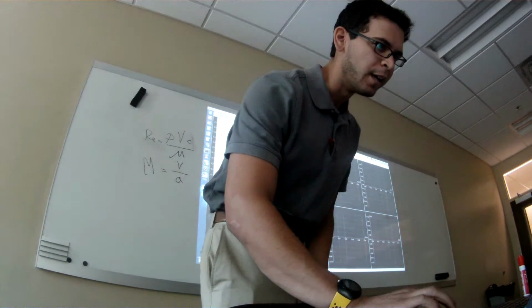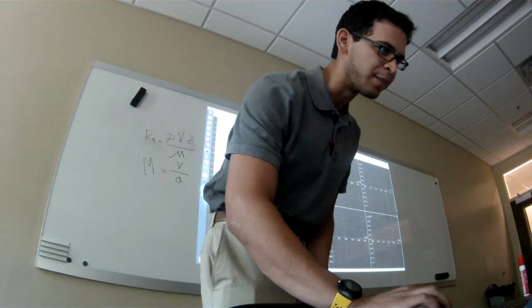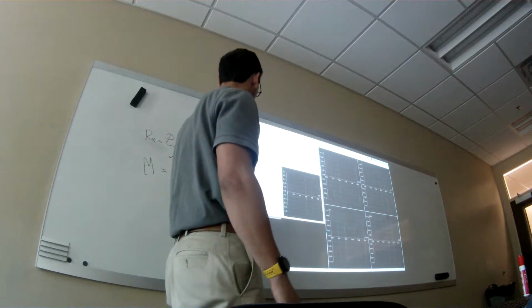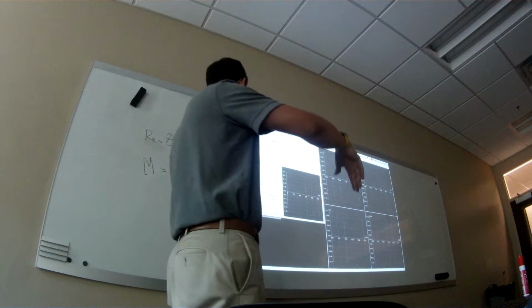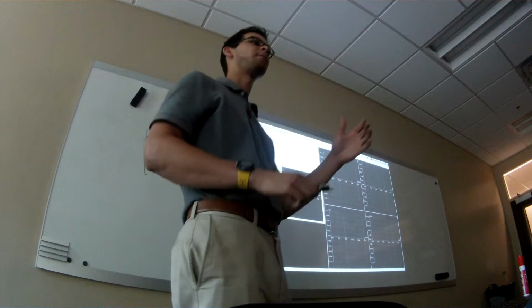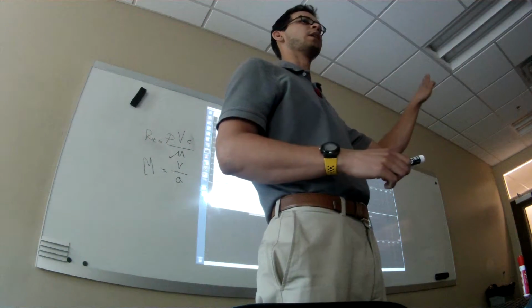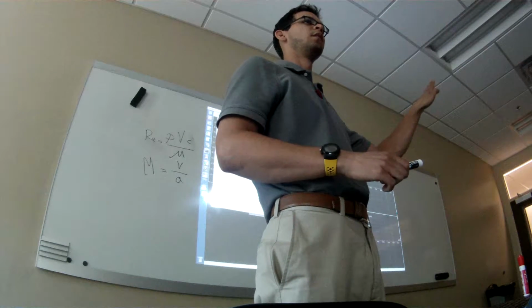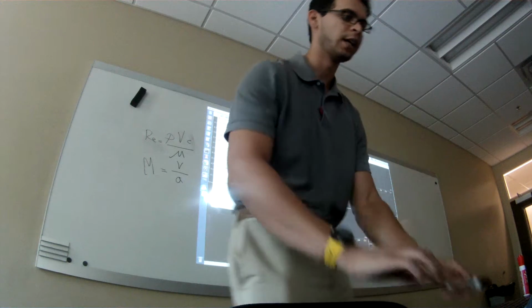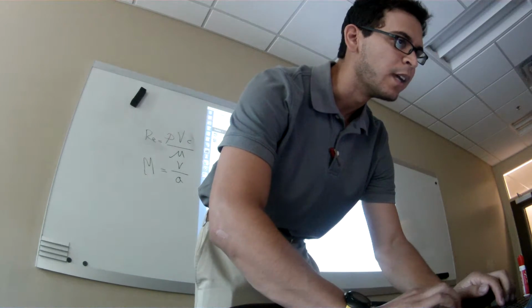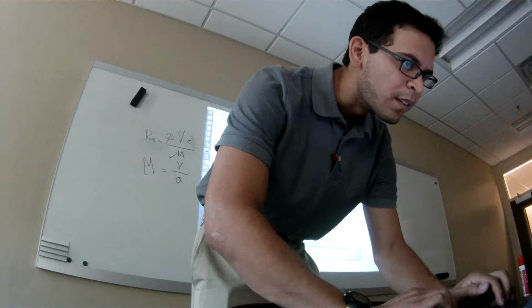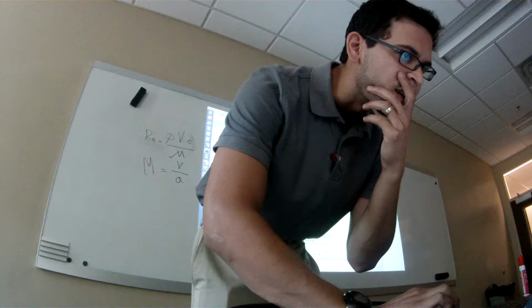And then I'm going to specify the angle of attack range, so I'm going to have it vary the angle of attack from -6 to 12. What happens if I go really, really big on the angle of attack? You're going to stall, right? So let's see, I think I have a video on this, stalling, yeah.